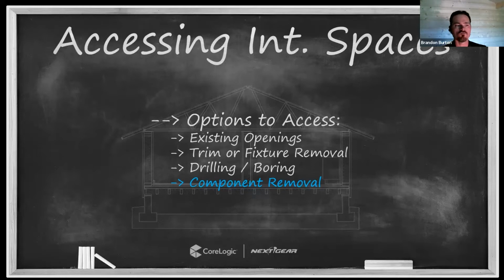And you'll be amazed, if you automatically always start with a wall assembly by drilling and boring and injecting air, and that's how you always start, and you start with a little less invasive approach first, give it 24 hours, you'll be amazed how often you can make better progress than you anticipated and avoid some of the restoration costs and repairs that you traditionally are adding and tacking on to every time you have a wet wall. So more on that in another episode.